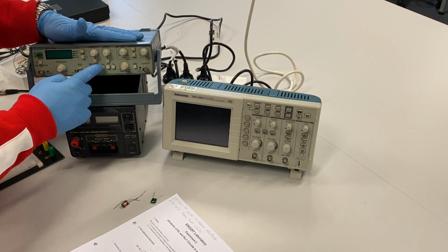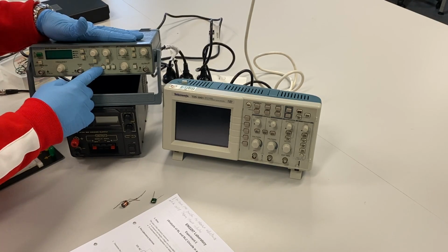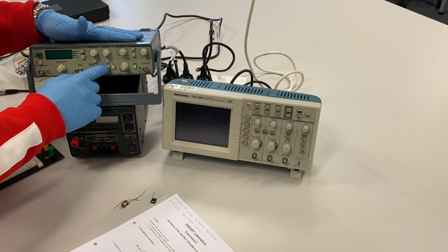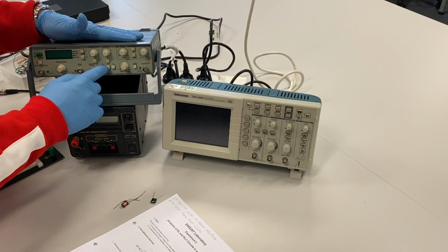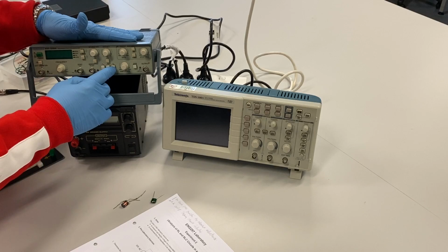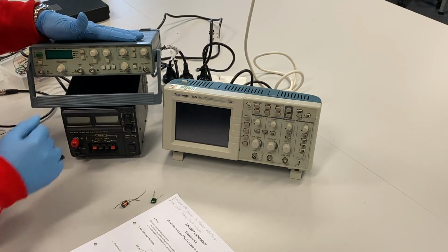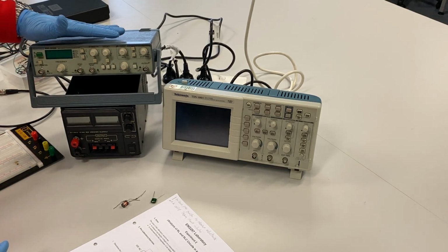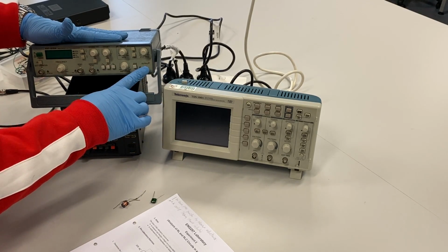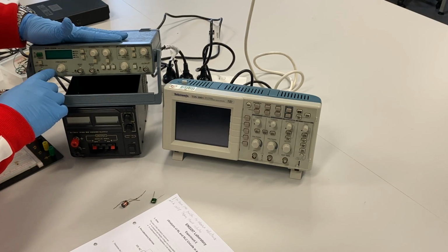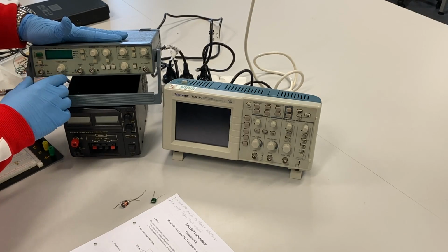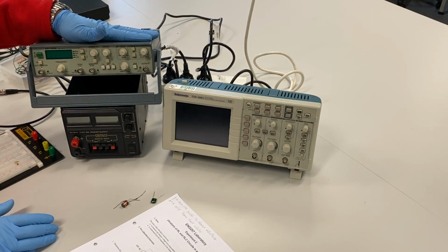We've got about 3 options, which is the sinusoidal signal, the ramp, which is basically like a triangular wave, but it only becomes a purely triangular wave if you change the symmetry to 50%. Then we've got the square wave. Those are the 3 types of signals that we can give using this function generator. And we just take our output from this output node, and we can change the range of the frequency from millihertz to megahertz using this knob right here. Right, I'll show you in a second how we can actually do this.